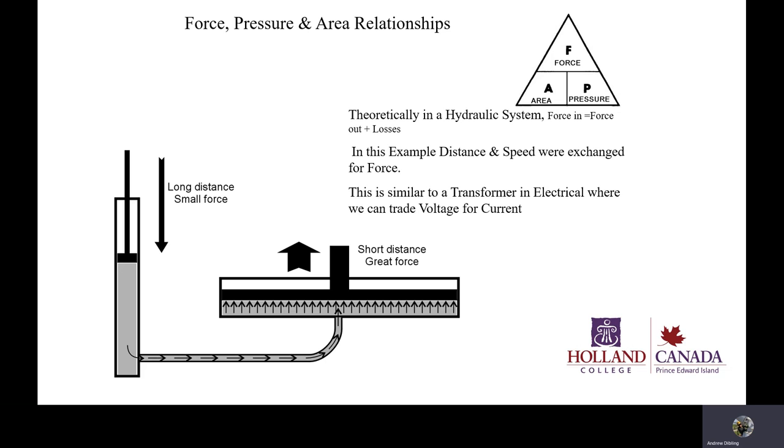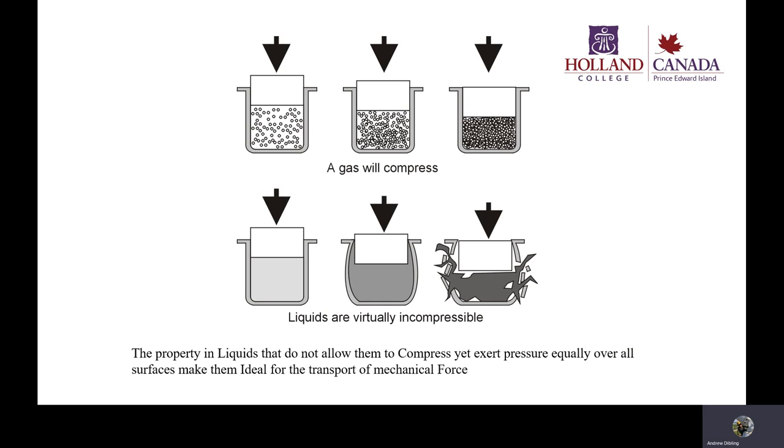All right, so this is your typical bottle jack. You'll also see this used in the car to apply the brakes. You push your foot down on the brake, it travels 3 or 4 inches. It's then put through a large diameter master cylinder, which concentrates the force on a small output, giving you a lot of pressure. And that pressure is then exerted on a large area on the calipers. However, the calipers move a millimeter at most. So the same kind of system. You're changing distance for force. Right. Okay. Moving right along.